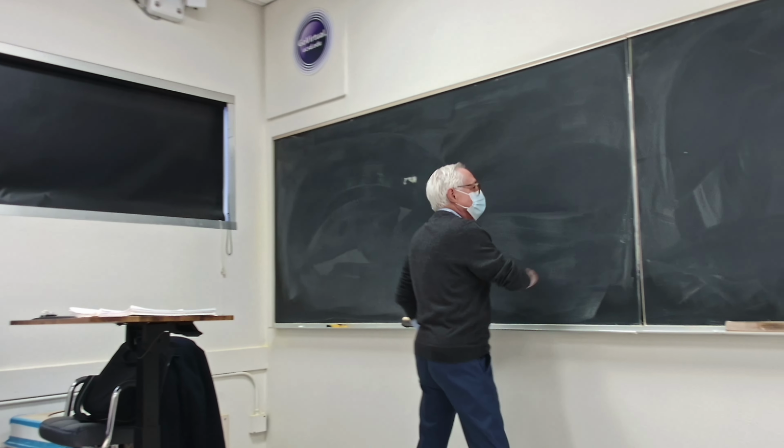Work out, of course, it gives us work. Then one inlet, one exit again. Z, no change practically in a turbine. Even if the turbine is the size of this room, so what? Delta Z, negligible.